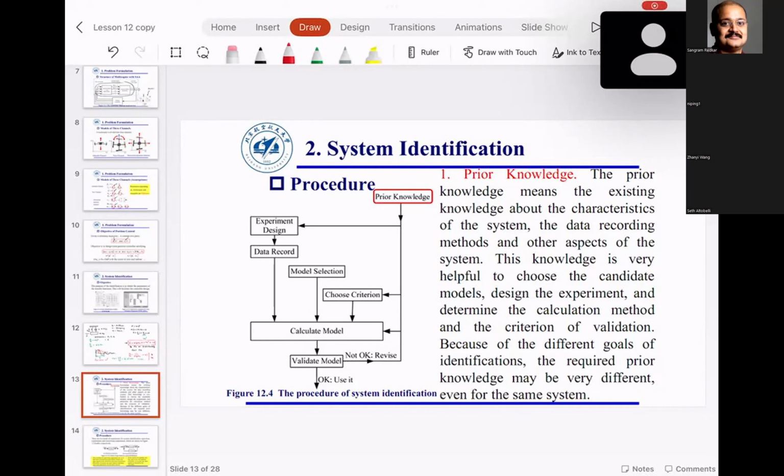And again, what you do is, you perform the same type of experiments to come up with the controller parameters, tune the gains, and basically control the system in those three channels. And there are different techniques for controller design, but at the end, you want to make sure that the system that you are going to design is simply stable.